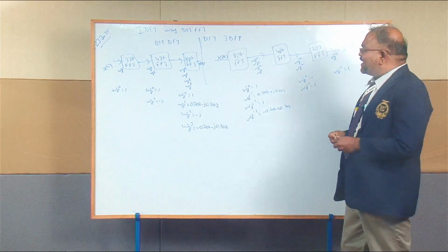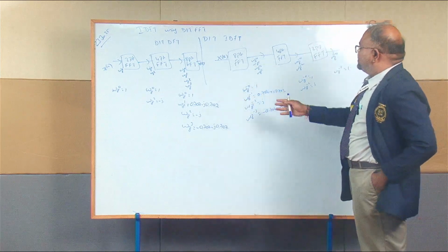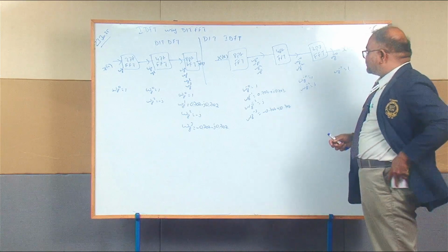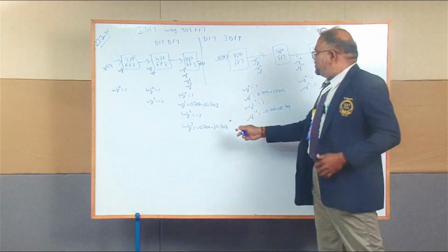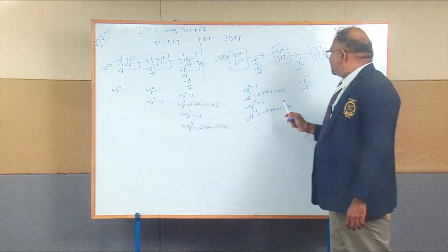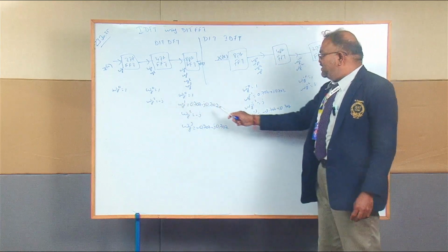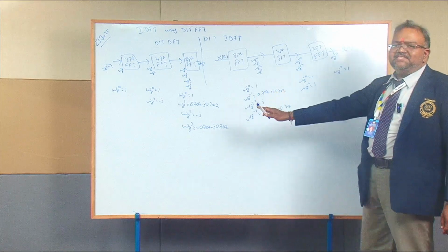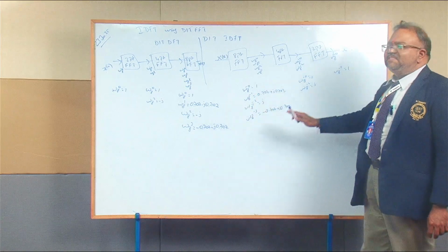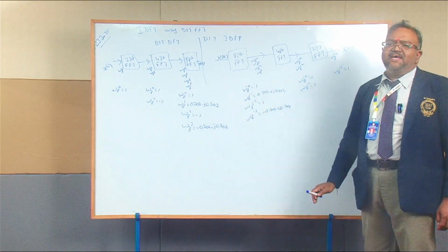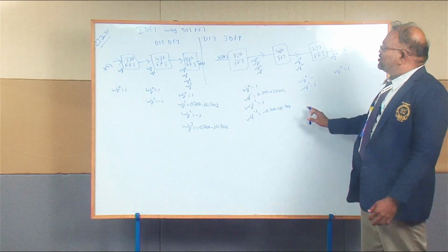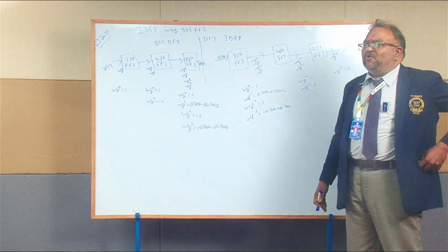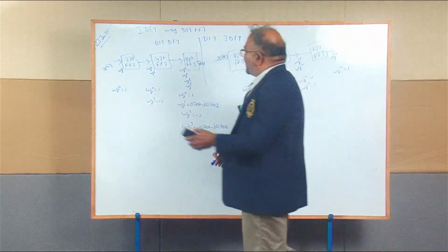Once we know that butterfly diagram, easily we can solve it. So, values will change here. Instead of minus j, we will have plus j. Here minus j, it will be plus j. Simply you can remember all the minus j in DFT will be changed to plus j in IDFT. So, this is the basic concept here. Using this concept, we are going to solve a problem for IDFT.